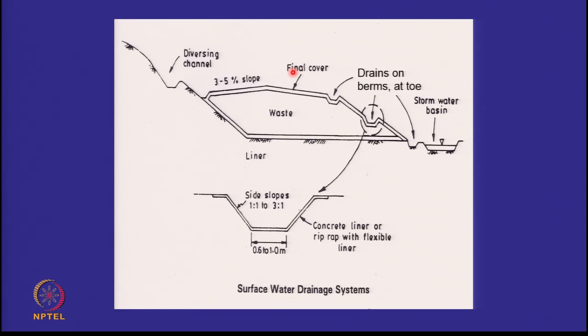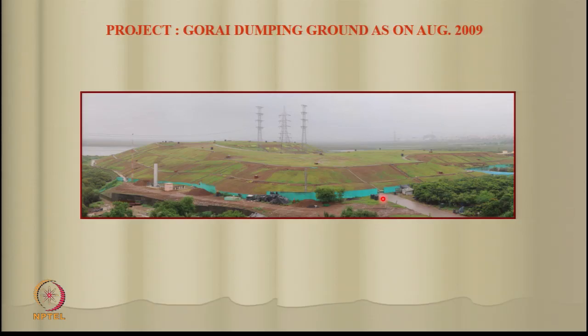Surface water drainage was another area that we briefly touched on. We did not do much detailing of surface water drainage because again it was hydraulic design, but we don't want any water to remain on top of the landfill. We don't want any water to come into the landfill from ground which has a higher elevation than the landfill, and what kind of diversion channels and drains and stormwater basins that we have to provide.